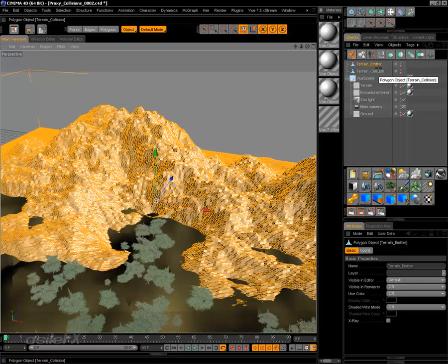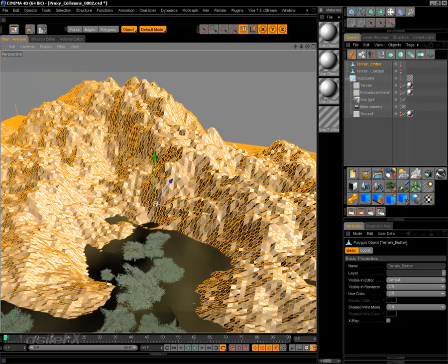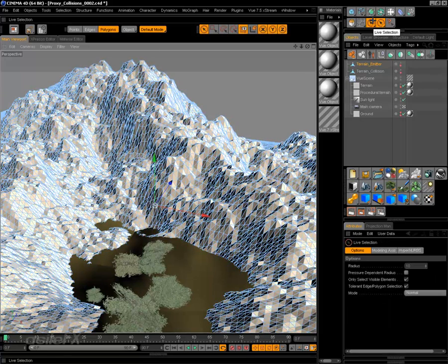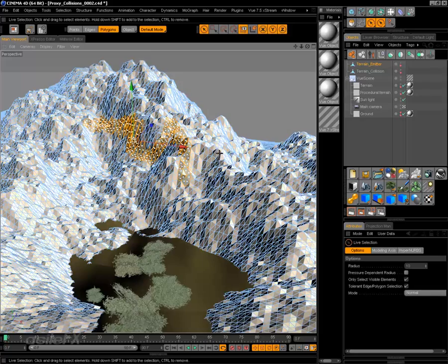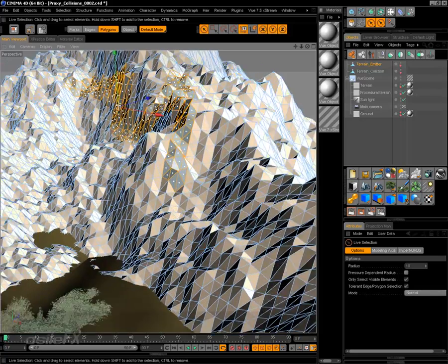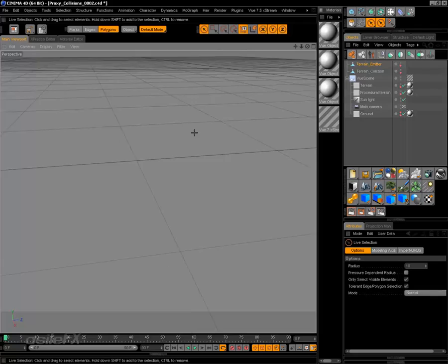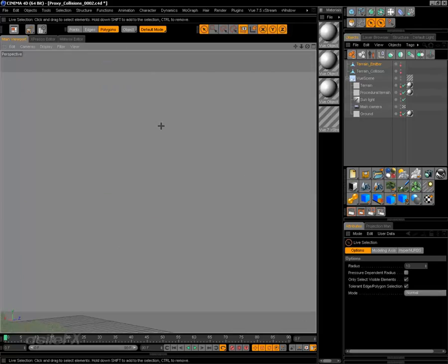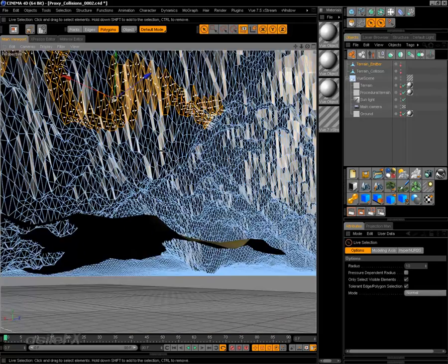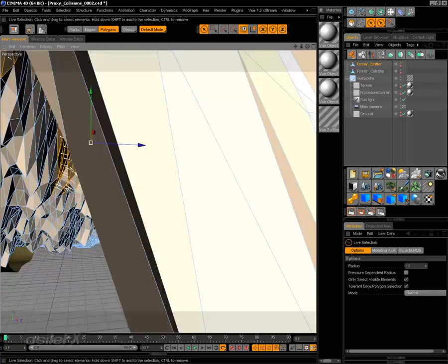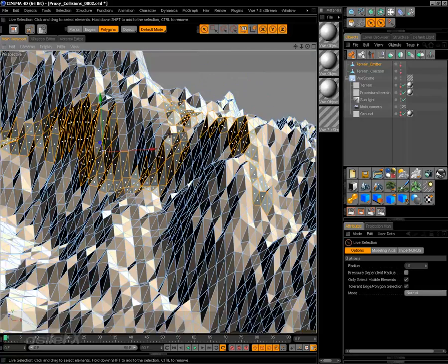And the first thing that needs to be done is the normals need to be inverted. If we go to the polygon mode and just use the live selection tool, we're going to take a look, and you can see the normals are pointing the wrong direction. If we go underneath, in order to see that better, all of the normals within a proxy point the wrong way, which could be some of the reasons why the proxy objects themselves don't work.